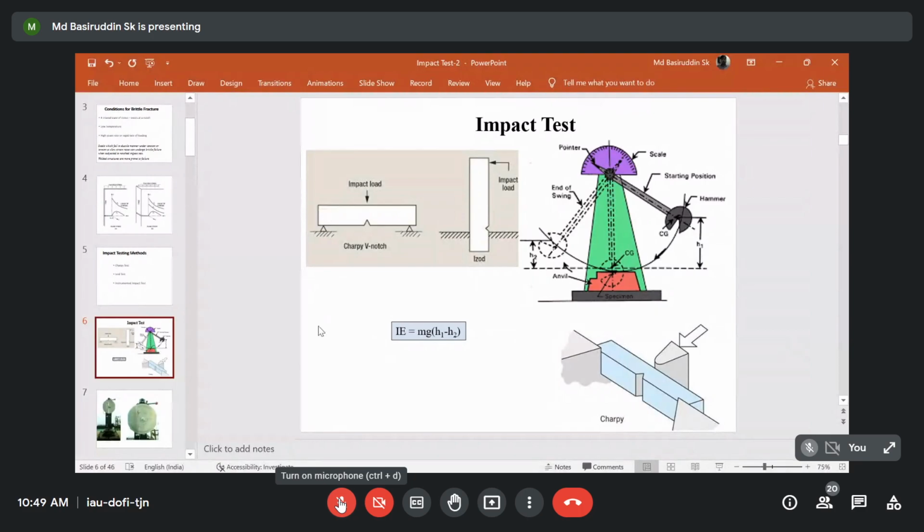If you see the schematic of Charpy impactors, it would look like this. Now you must have certain impact testing machines, and impact testing machines will look like this. Generally, after preparing the specimens, we need to put the samples over the anvil, and you need to choose suitable positions. And then we generally put some notch intentionally such that localized deformations happen in front of the notch.